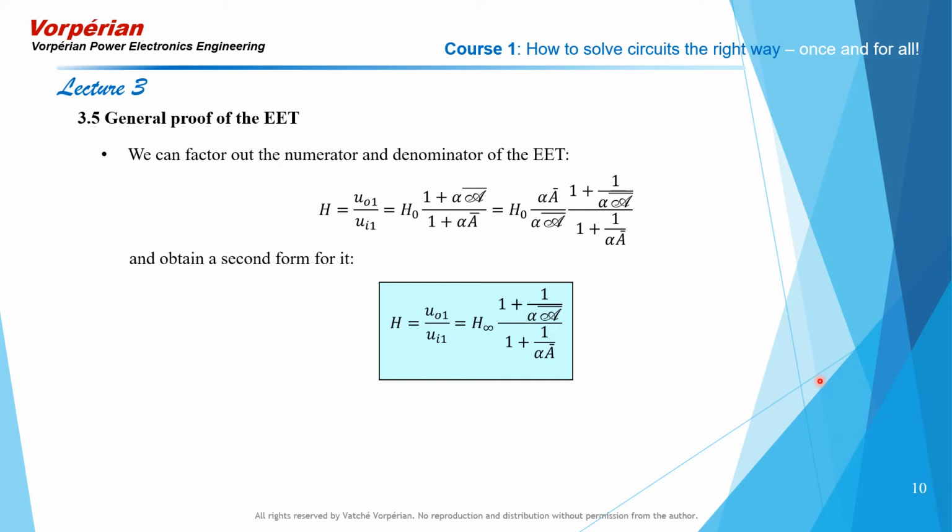So it is reasonable to say, let me assume it's infinite and see what my transfer function is. For all those cookbook op-amp circuits, you have computed all those gains with ideal op-amps with a gain of infinity. It turns out the gain is not exactly what you obtain from the perfect ideal conditions of infinite gain. It's slightly different. How slightly? It is different by this factor here. But let's leave that for later, when we do actual examples.